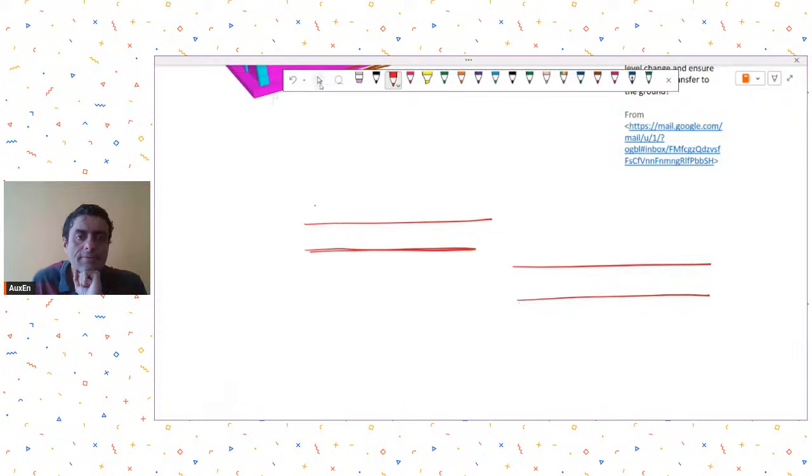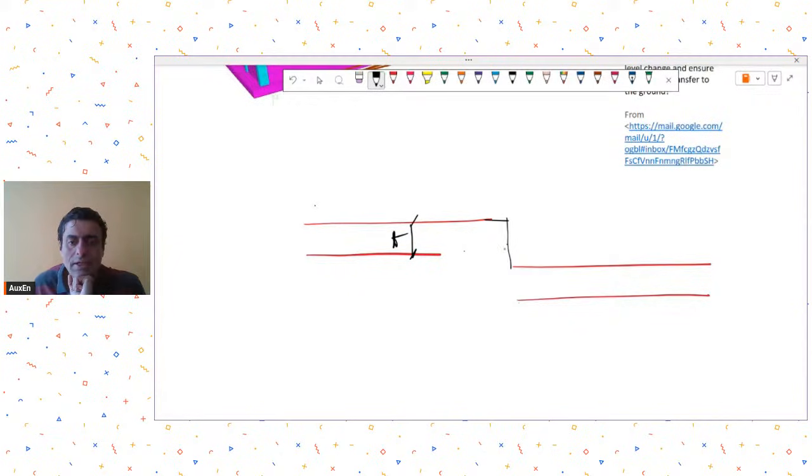So generally, we try to do it this way, that you try to create a 45-degree angle over here, okay? First of all, ensure that at this junction, let's say this was your junction, this was the line. Now you first of all make an offset which is equal to the raft thickness over here. So make an offset from this line like this.